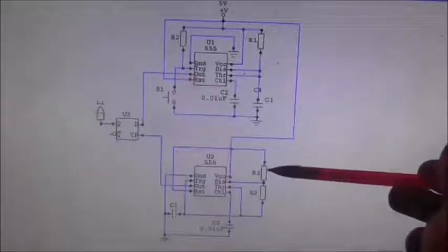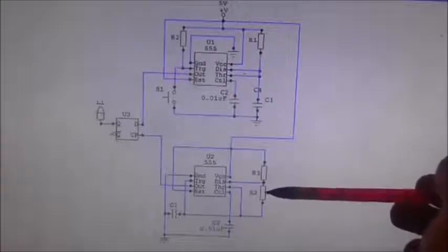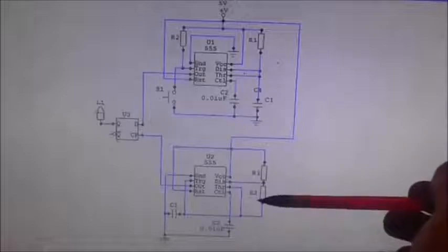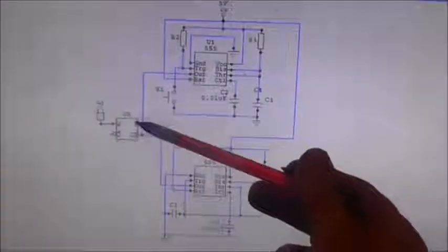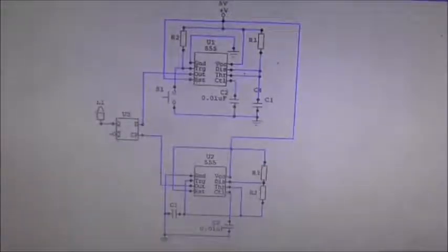If we change the values of R1 and R2, we can make the clock go faster, and we can make the timer much more responsive. So as soon as you press the switch, you'll get the data going through, and as soon as the switch goes low, you'll get the data going through, or at least within milliseconds, rather than the half a second that we had there before. And that's about it for the timer system and for the D-type flip-flop.